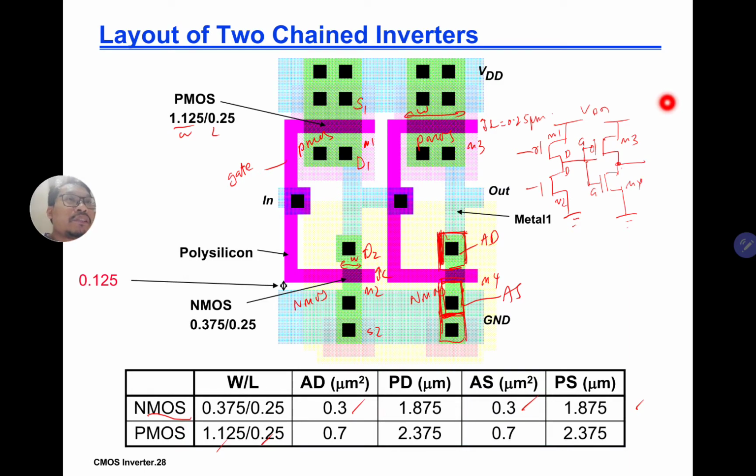You see here, this is a drain. The drain is connected to the gate of the next transistors. And where is CL? CL is right there, on the output node. Here is your output node; output is here, input is there. Let's call it the load node, the loading node that we are interested in finding, because the speed of the first inverter depends on CL. So the CL that we're going to look at is here.